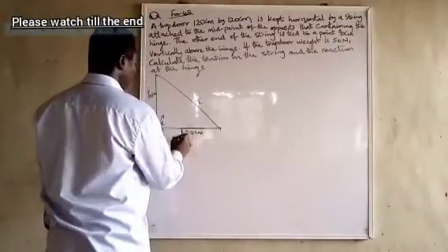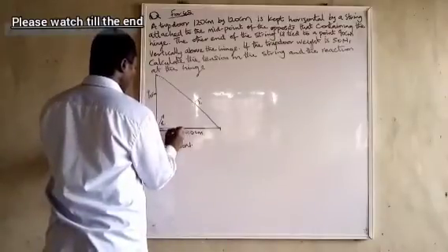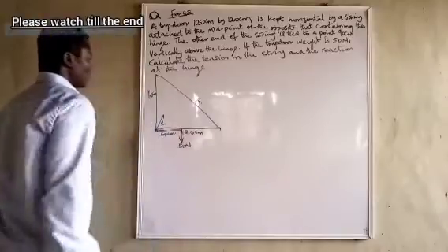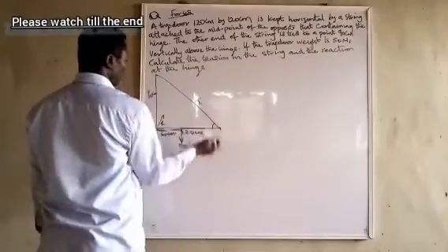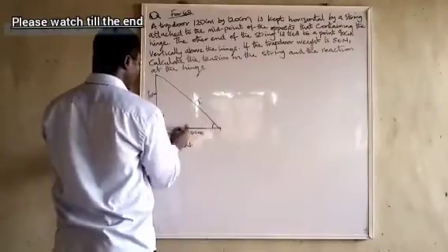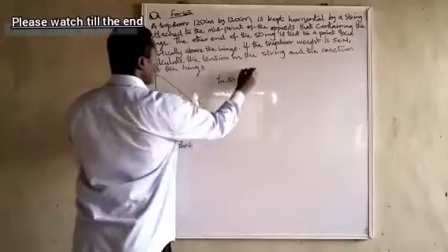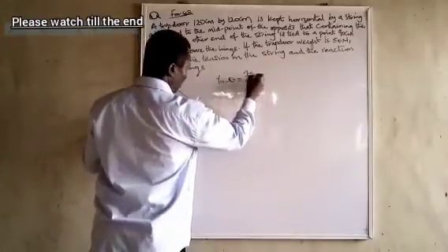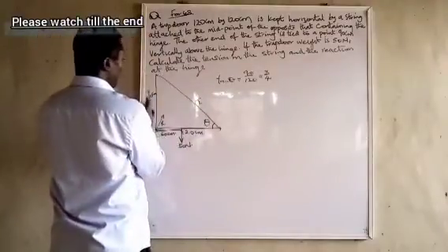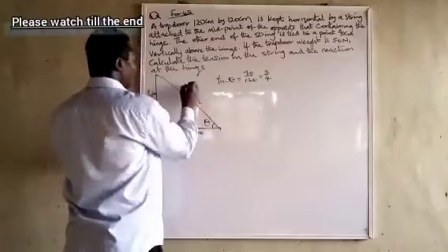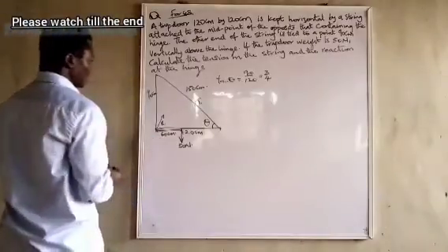This is 50 Newton. And from this place to this place will be 60 cm. And with this one, we can know something about the trigonometric ratio here. For instance, we can see that tan theta is equal to 90 over 120, which is 3 over 4. At the same time, we can know this place, because this is the square root of 90 squared plus 120 squared. From the ratio, we can see that this place will be 150 cm. So we can work this easily now.